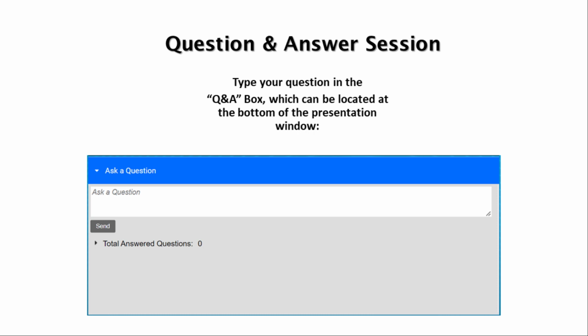Fantastic. Here's your next question. Is there any chance of having peak tailing after long HPLC runs? I'd say it really depends on the method conditions that you're using and perhaps even the age of the column, and maybe also the identity of the compound that's tailing.